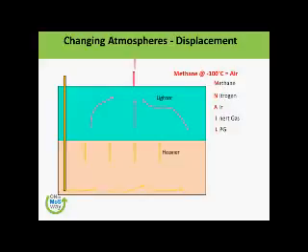So whatever is heavier, we introduce it from the bottom. Like you have seen here, you may be able to see the lines. We are introducing it from the bottom, and it is pushing the lighter gas out from the ventilation line. So let's press on further.